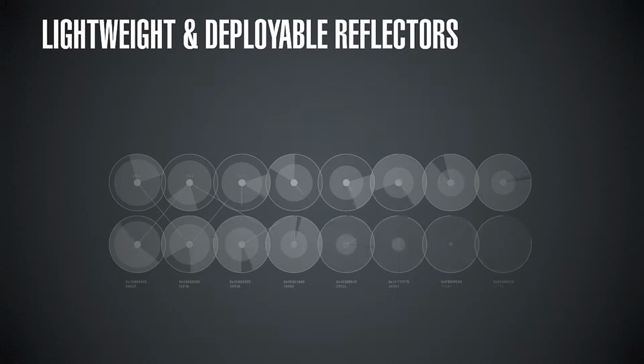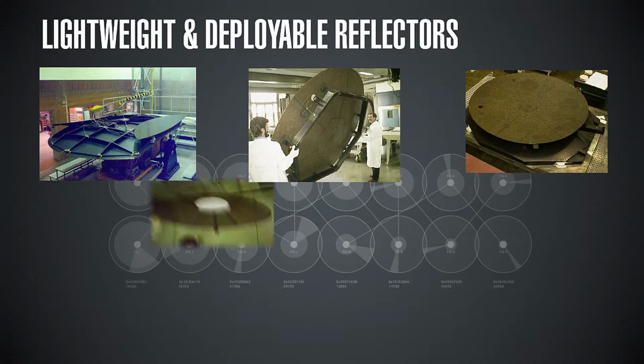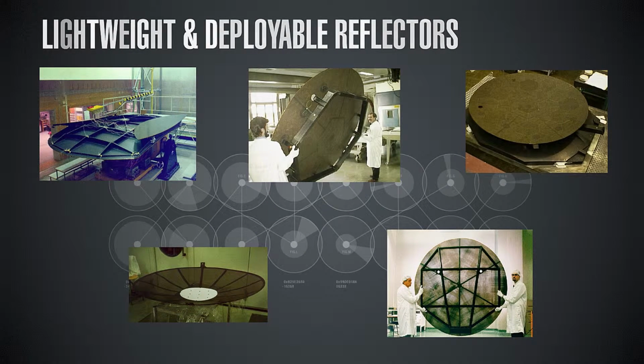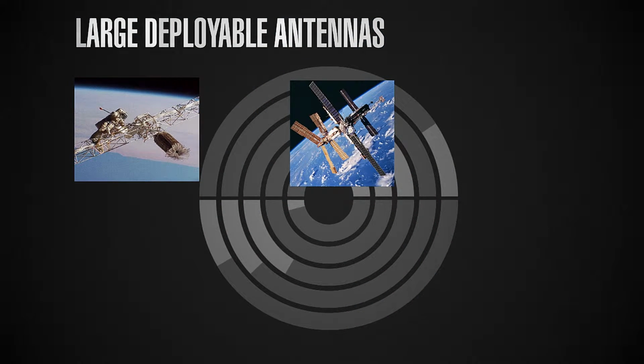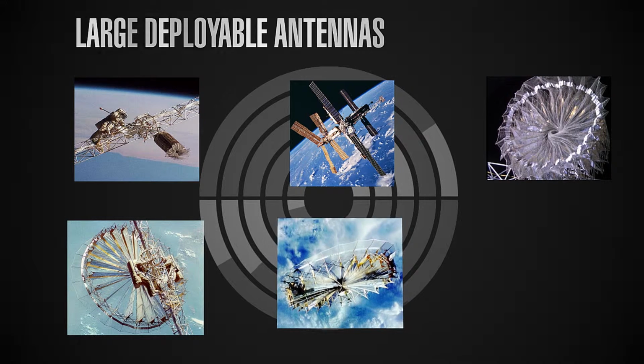In the next slide, we see the realization of large reflectors. Up to a certain dimension, these reflectors can be made with a solid design, in this case carbon fiber, which is very light, but still strong enough to survive the stress of a satellite launch and mission. And this was a reflector with 4 meters in diameter, so in order to accommodate the reflector on the spacecraft, it was conceived with foldable tips. So this was somehow reducing the dimension. But other types of reflectors, larger also in diameter, were designed and then realized.